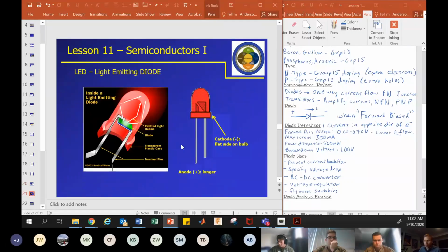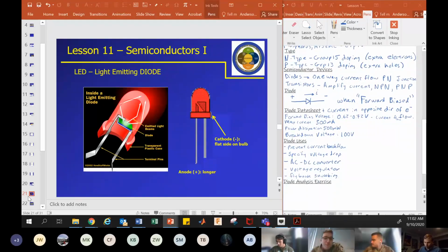More common is an LED. We will use LEDs. So we've talked about these already. The anode is the long end and the cathode is the short end, and current flows from A to C, alphabetical order. So make sure they're plugged in right.